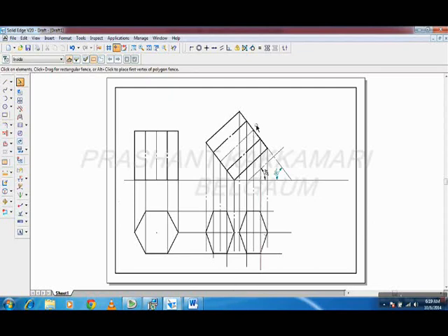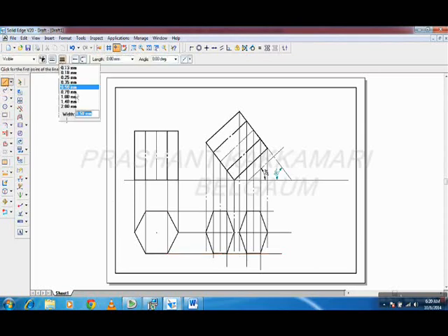So now I have drawn the top face here, bottom face here. Now join the edges. See here, now two edges are on the same line. Again here two edges are on the same line. Or the face is parallel to the observer. So draw that by thick line, 0.5 mm thickness. So from this intersection to this intersection, which is visible or towards the observer. So this is nothing but from D to what? See here, A, this is D, G, H, I, J. So G to J it is. So these two lines I have drawn.